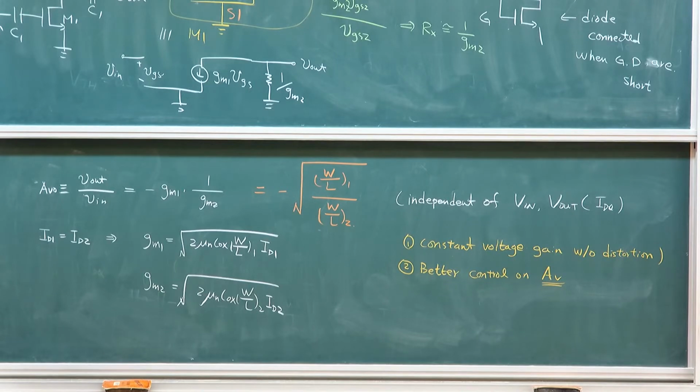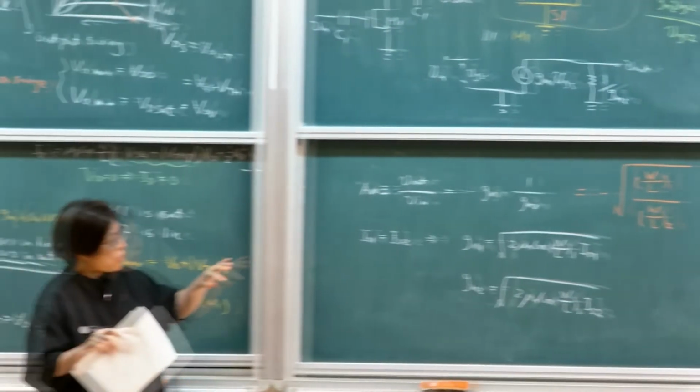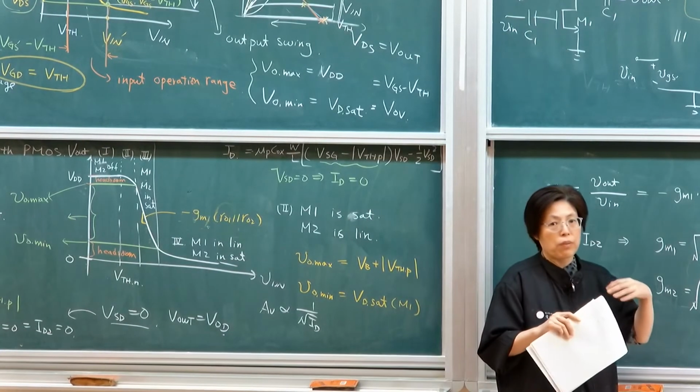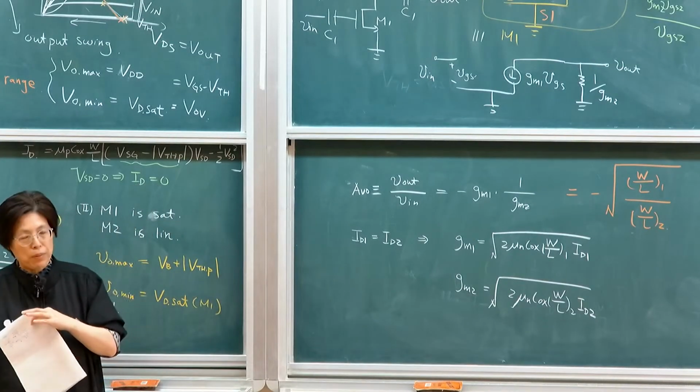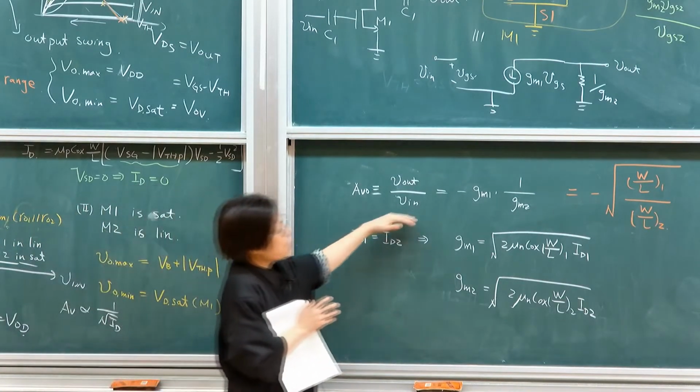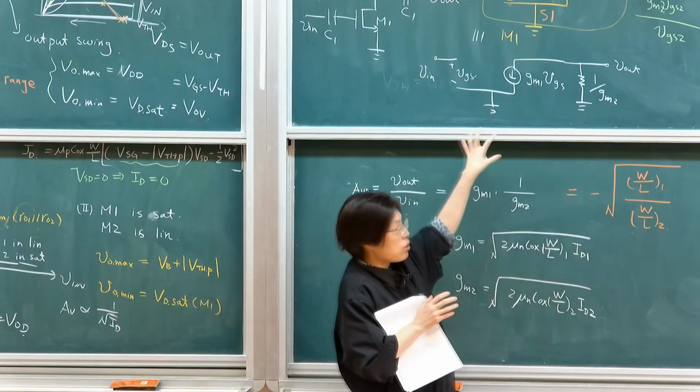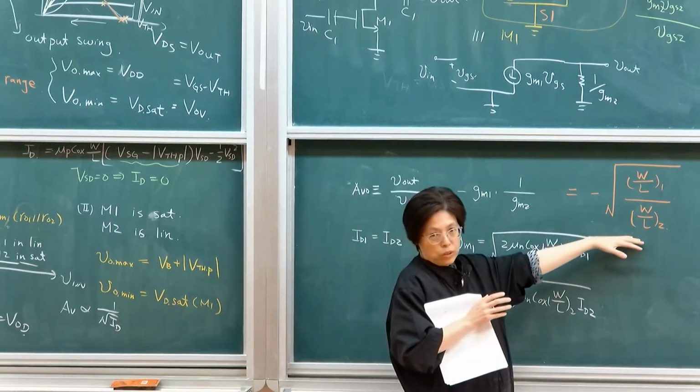And then when you actually use the operational amplifier to do calculation, the actual gain depends on the external circuit rather than the open circuit gain. In real operation, you use it in a feedback loop, that sort of thing. So precision of gain is not necessarily very important when you're doing operational amplifier design. But if you want to have a precision gain within a small circuit, then this is the way to go.